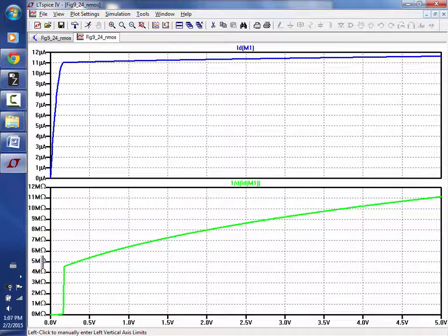So what did you use for your hand calculated value for R out? What was the value you used? Okay, so if it was 8 point whatever, and you were operating at a smaller voltage, say down over here, could be way off, right? So this tells you what the output impedance is for a specific operating condition. And then once you've determined that, you can be precise. You can go look at this plot and say, I used 5, a better approximation is this, or I used 8, which is out here. Better approximation is 5, but 8 is a good value for being in the ballpark. Does that make sense?